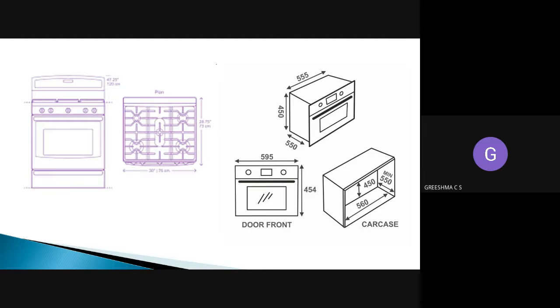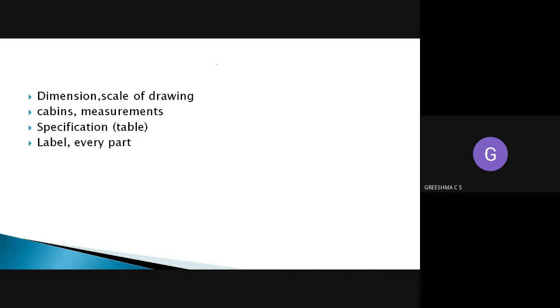A 5 mm plus or minus may occur. That may also occur in the similar case of 454. You will not be able to depict exactly 454. Sometimes it is 450, sometimes 452, 453, or sometimes 457. A plus or minus 4 mm can occur there. So that is called tolerances. That is, some variations in the measurements will occur. So you can allow some variations. A 5 mm more or less is no big problem. That is called tolerances. So that also you have to mention.